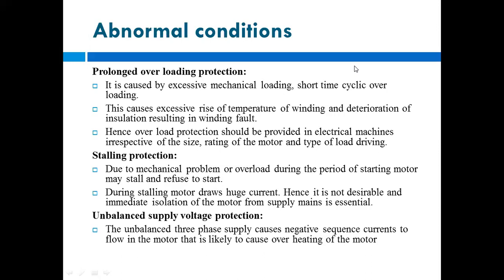Actually, the rated capacity of that machine is already given, which means up to that particular point you can connect the load. But if you increase the load on the motor, you can connect that load for only some time, or a few minutes only. If that load persists for more time, it will damage your motor. So we have to protect the motor against such types of loads. That is nothing but the prolonged overloading protection.